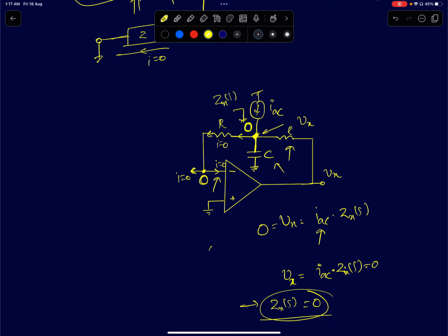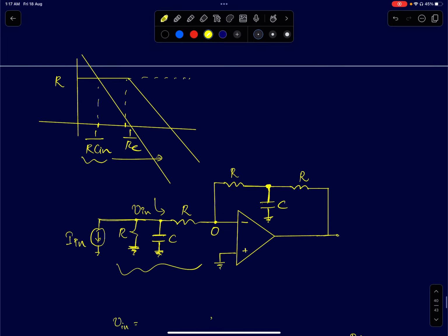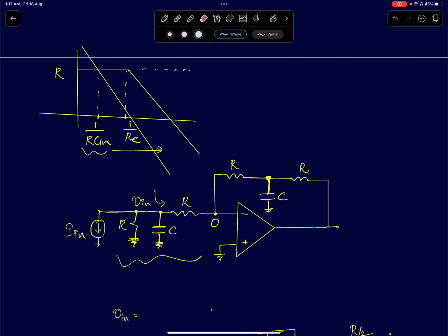Now finally, we come to the third part of the question, which is you're supposed to find out the transimpedance amplifier's gain, which is V0 by In. So here I've removed all the DC sources, I've short circuited the VCM, I've made it 0, and I've open circuited this current source, the DC current source is removed, and this part of the network. Okay, so there is In and a capacitor Cin coupling it to the op-amp circuit. So this is the circuit.